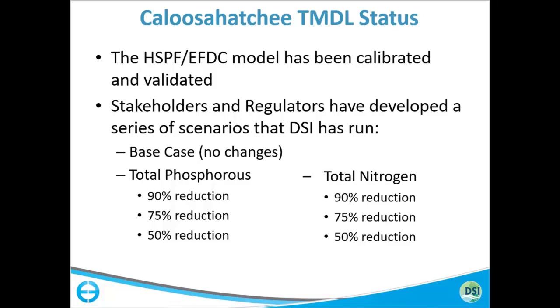When you are doing this kind of sensitivity study, it's always recommended to change only one parameter at one time, because if you are changing multiple parameters, it's so hard to distinguish which parameter caused that variation in your system. So this is just to give you an overview of what we did and how to use EFDC Explorer to be more insightful for management purposes.